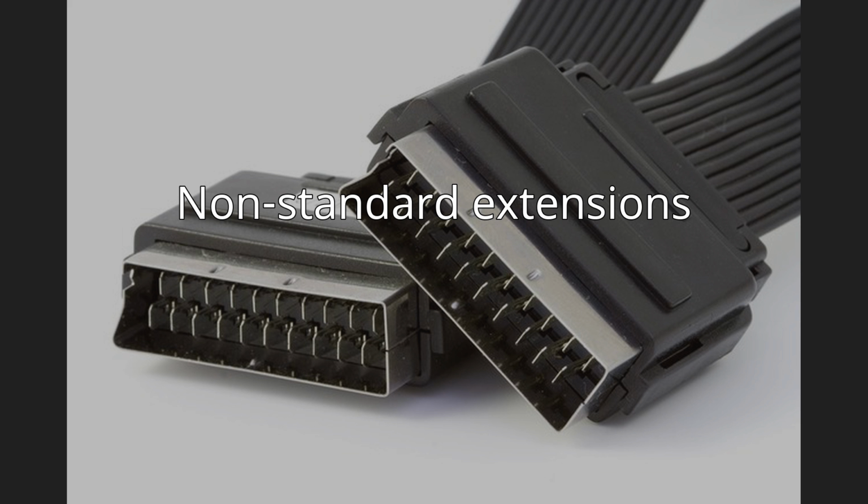Also, if a compatible TV and a compatible DVD player, but from different manufacturers, were interconnected, the surround might not work, and only the stereo sound from the DVD player was available to the TV, because some manufacturers did not use S/PDIF, but their own protocol. Also, this connection might be lost if the DVD was connected to the TV indirectly through a VCR in daisy chaining mode. However, some VCRs allowed the pass-through of these signals.